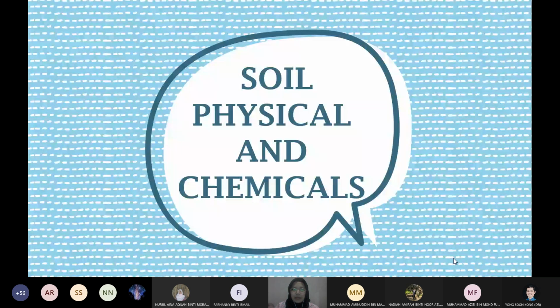Next, 25 ppm paraquat was used in Sekinchan, which affected the paddy physically. It is said that the dry weight, height, and root dry weight of the paddy decreased by 10, 8, and 37% respectively. So due to all of these possibilities, an environmental sampling plan that includes soil, surface water, groundwater, ambient air emission, sediment sampling, microbiology, fauna, and paddy sampling needs to be conducted to assess possible contamination due to the factors mentioned.